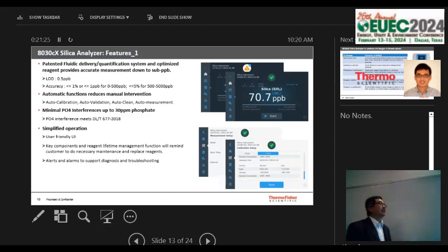Everything is very clear. And you can go to logs. You can look at, hey, what was the last time it was calibrated? What was the factory calibration? How much difference are they? Obviously, if someone messed up, you can clearly see the factory calibration slope was 100, and now you're getting only 20. That means probably something messed up, right? So that will give you a track record of fixing the issue rather than worrying about what went wrong. Yeah, all the data logs are there. You can look at the past 3 months of data, 6 months of data. The data are supposed to be good for a year. So anything you want to trace back, you can trace back.